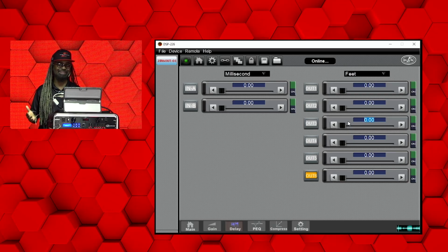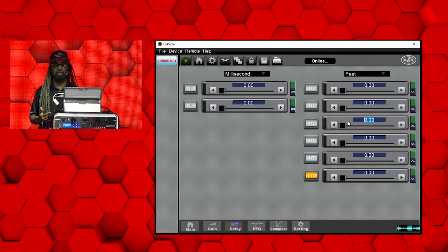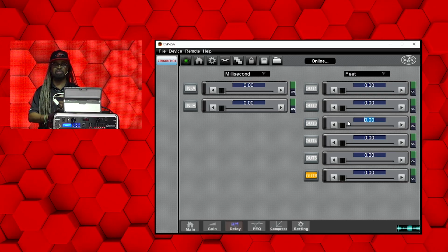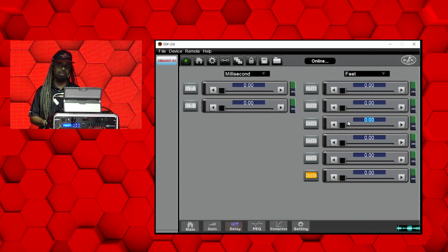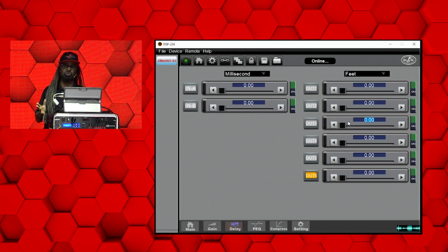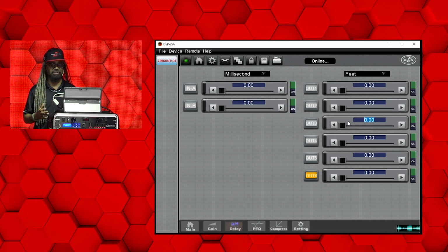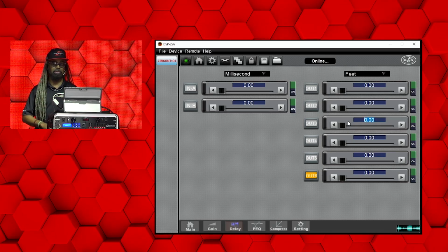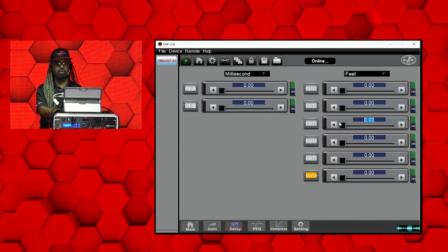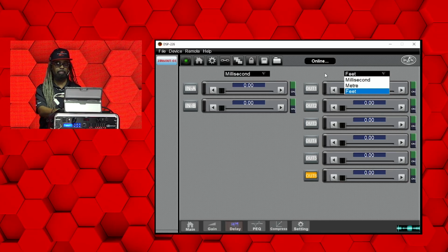That's just an example. There's so many different ways you can set up your delays depending on if it's a fill, if it's a sub, where the speaker is placed, and what type of speaker it is. So you always want to make sure that you're not looking at exact hard values every time you look at delaying a speaker or a sub. But you have the ability to do your delay and various increment measurements.